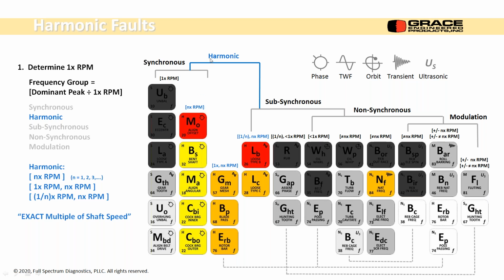There's always some overlap. Harmonics are coupling misalignment, bent shaft, another coupling angular misalignment, cocked bearings, and even that animation I just showed you this morning of the bearing and the balls going around, it had a cocked inner race. So it was rotating and producing usually a twice running speed harmonic. So harmonics, these are 1 and 2 times usually.